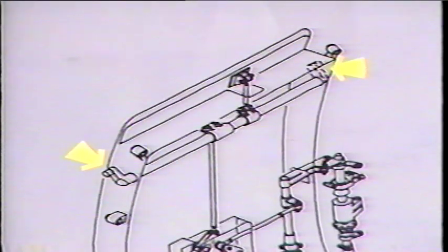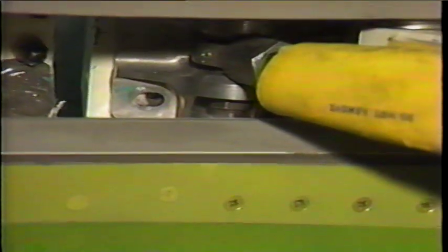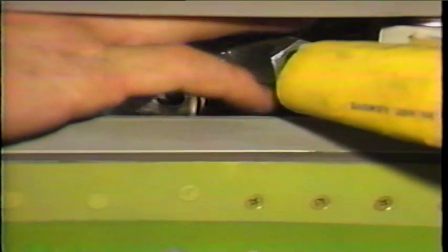If the latch cams are installed, check that the 2 top latch rollers on the door contact the latch cams on the body at the same time. If this condition is met, then no adjustment to the serrated plate is needed. If the forward latch roller is too close and the aft latch roller is too far from the latch cams, loosen the jam nuts and lengthen the guide arms slightly. Remove the bolts and move the support bracket forward 2 serrations. Repeat the check for simultaneous contact of the rollers to the cams.